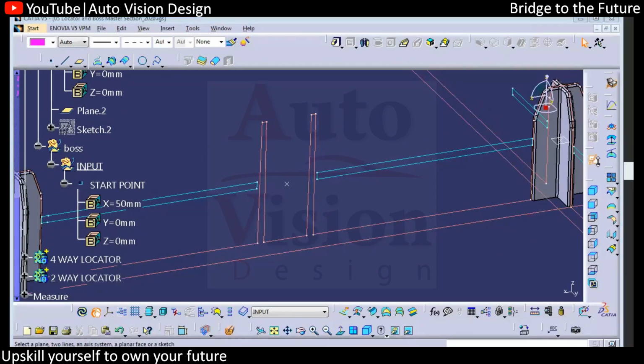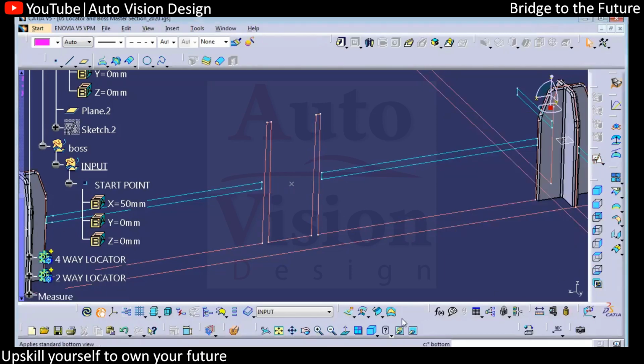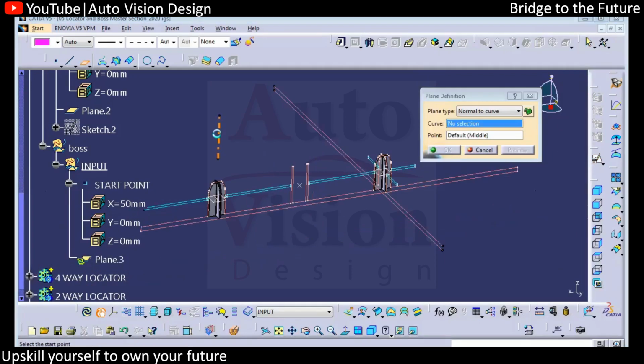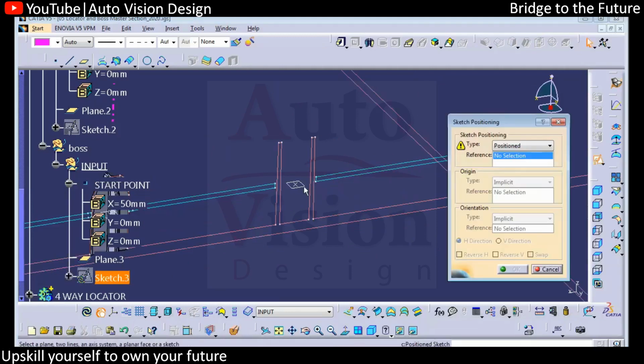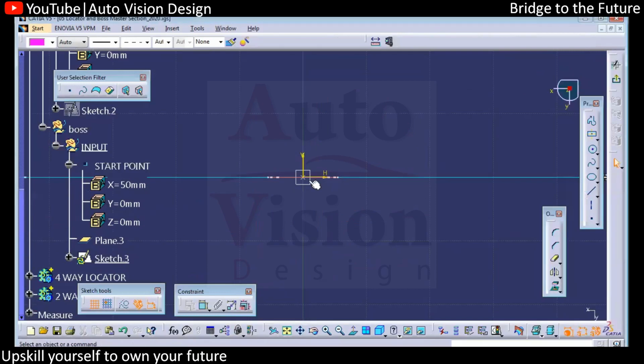Position sketch, we can go. For that, we require a plane. So we'll add the plane, normal to the line, passing through the point. On that, we can add a sketch. We can select the plane, we'll add the projection point. Then you can add this. We'll click on OK. Then again, we're going to add the circle.